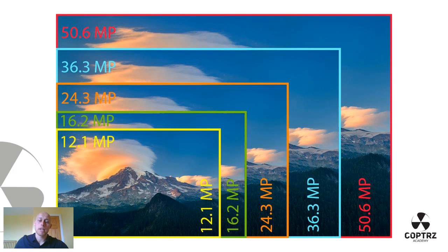When it comes to megapixels, this is going to be really important for inspection, because every single megapixel that you see is basically a point of interest, so you want to get as many of them as possible. When you are looking for cracks, deformities, or something that's not supposed to be there, a larger megapixel camera will put more megapixels on that feature. So in post-processing, you've got more megapixels that make up that single crack.